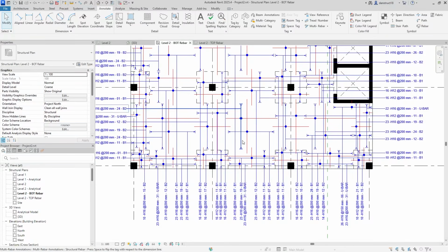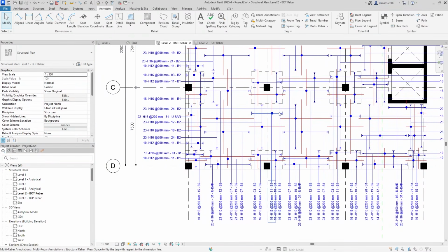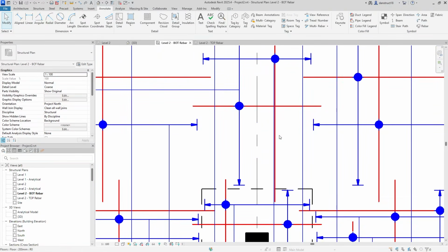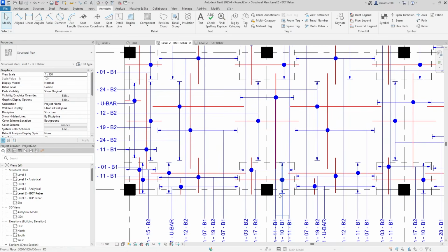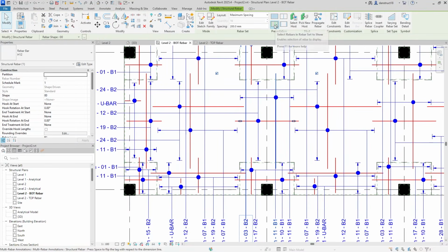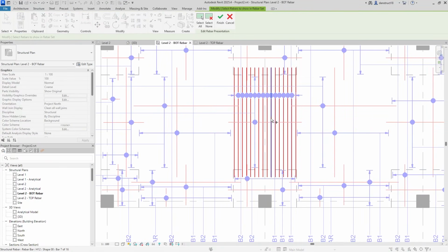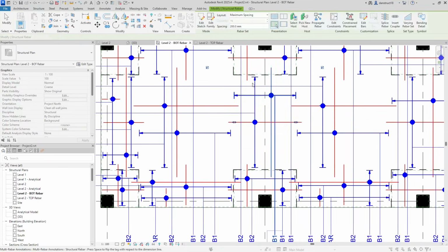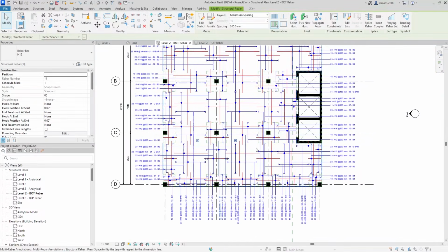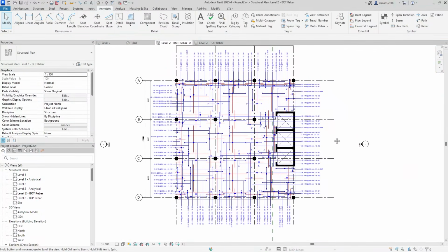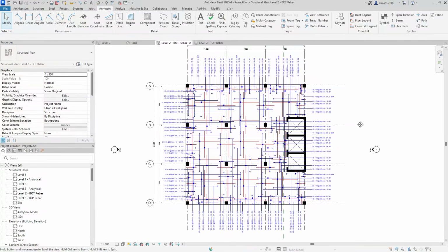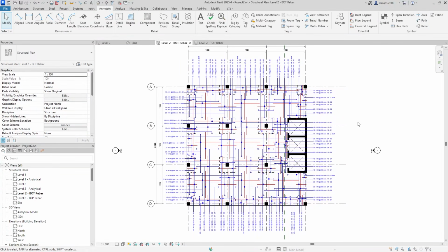Now, once you are done, you want to make sure that all your tags here are not clashing with any of the bars. So we can see this one in the process of trying to make room. You can see it's clashing with the bar. So instead of just trying to find a way around, you can as well also select the bar sets, then click here on the presentation, and you can just go ahead and change it to be another bar to show in sets. So there's always a way to manage your presentation. All right, good. Isn't this lovely?